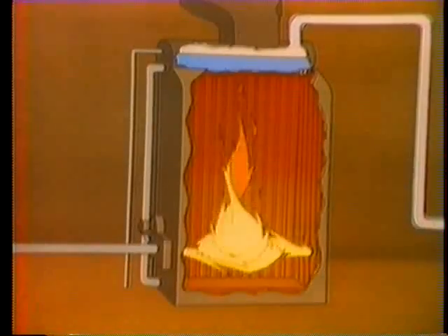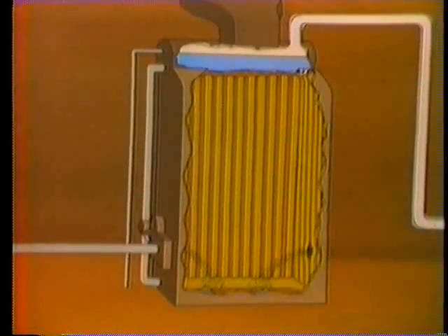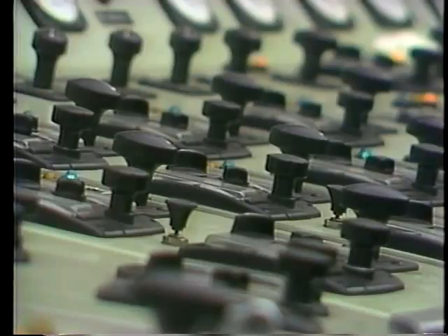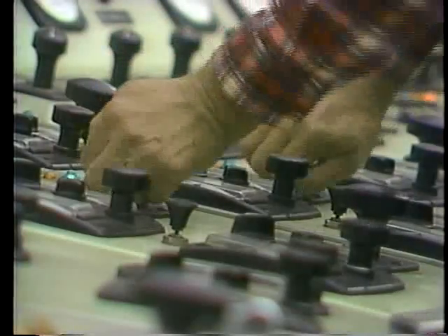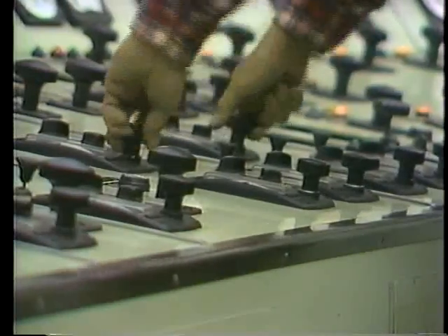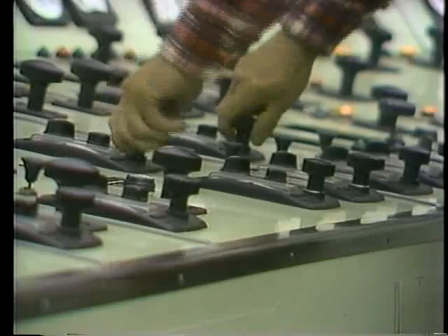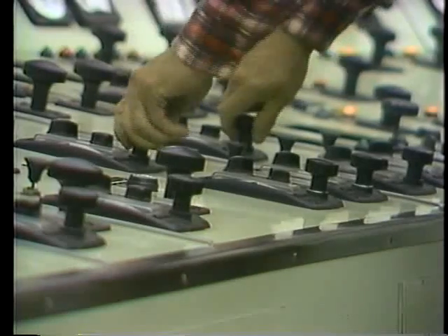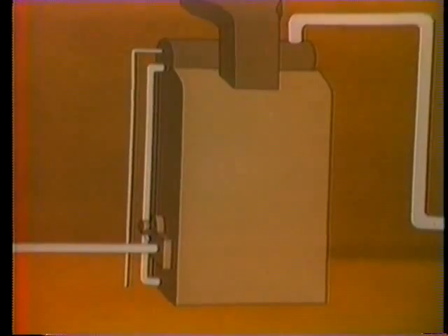If the boiler flame goes out, you have only seconds to respond. In many cases, procedures will indicate that the first steps in dealing with a loss of flame are shutting off all fuel flow to the boiler and either maintaining or increasing airflow to purge the boiler of all combustibles. Unless action is taken immediately, the boiler could explode.